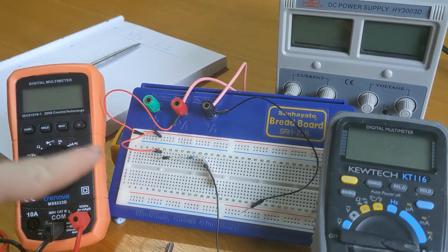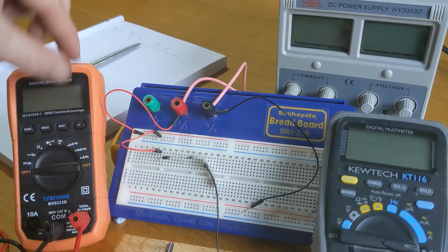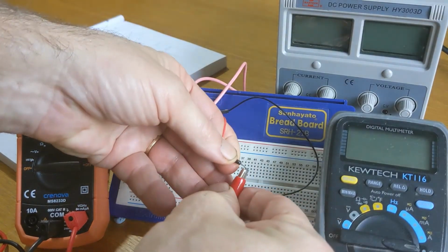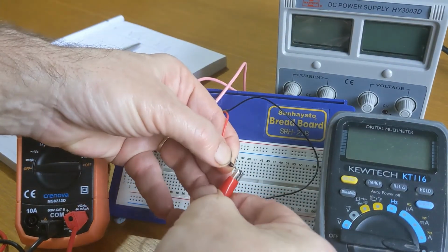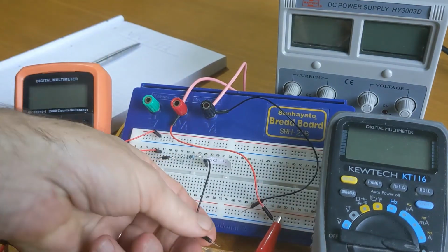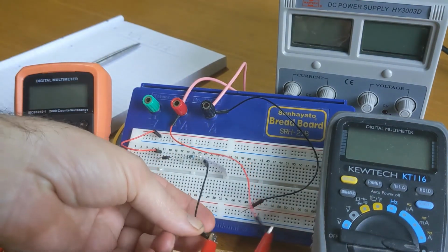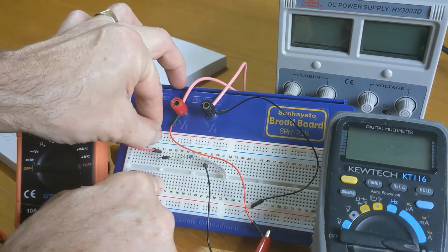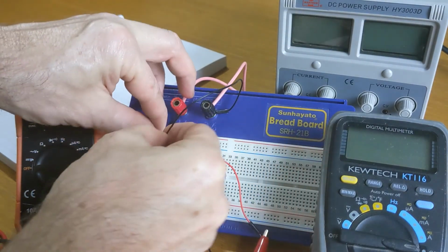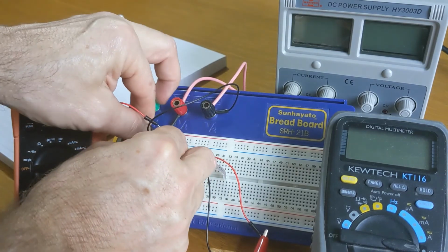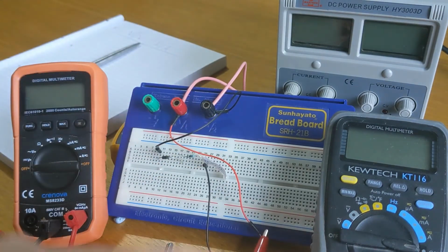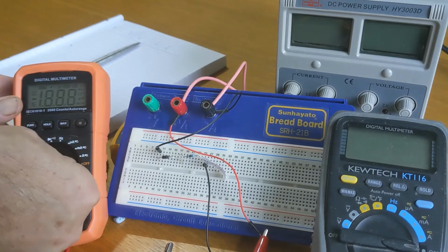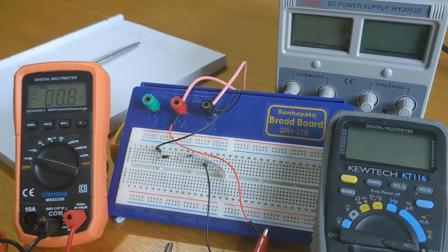Now the first thing we're going to need to do is to adjust the wiring on the breadboard slightly so that now the current is coming through the ammeter, through the resistor, and then backwards, if you like, through the diode in reverse bias and then back to the digital power supply. So we've changed the polarity. Again, we'll be on the voltage setting.